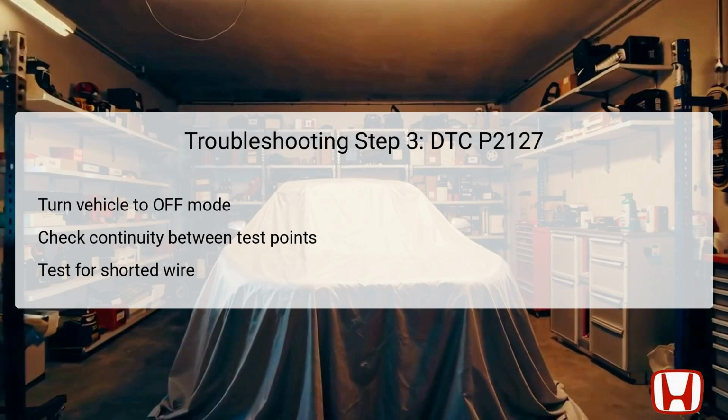In this step, you will begin by turning the vehicle back to the off position and jumping the SCS, System Configuration Setting, line using the HDS. Wait for more than 1 minute before proceeding to the next action to allow the system to reset any configurations. Disconnect the PCM connector A, 50P, to isolate the PCM from the APP circuit.